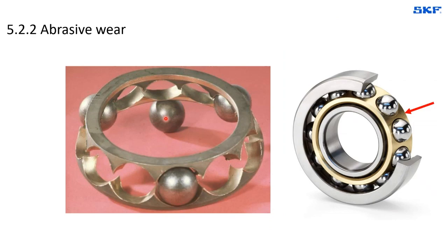So the cage is, no question, one of the weakest elements of the bearing, and is not supposed to do an extremely difficult job under normal operating conditions. But when things go wrong, in this case with the lubrication contamination, they can suffer greatly because they are going to be much softer than the material of the rings and the running elements.